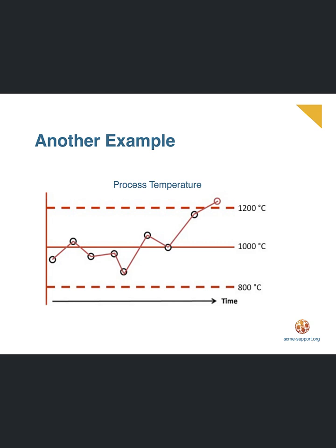At that point, the technician's standard operating procedure would probably be to stop the process and determine the cause of the temperature spike. By monitoring the process this way, it is easy to pick up on a process change, such as the temperature increase. Normally, there was something out of the ordinary that occurred to allow the temperature to rise out of the acceptable range.